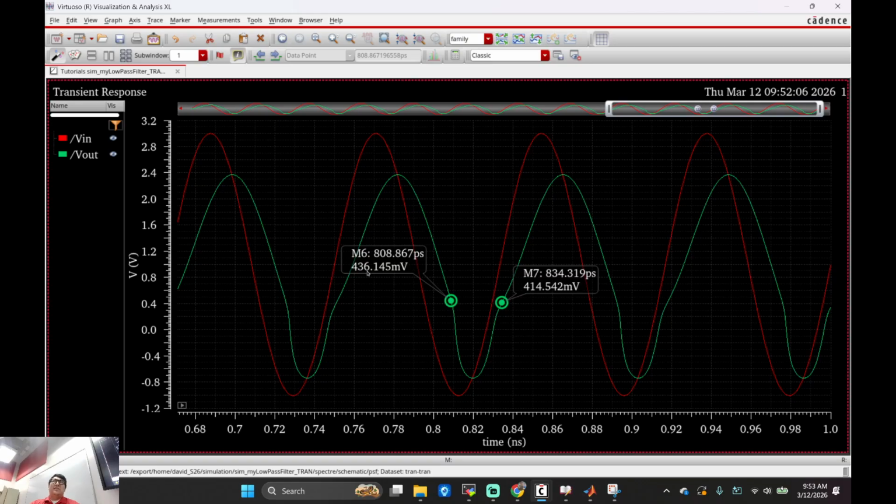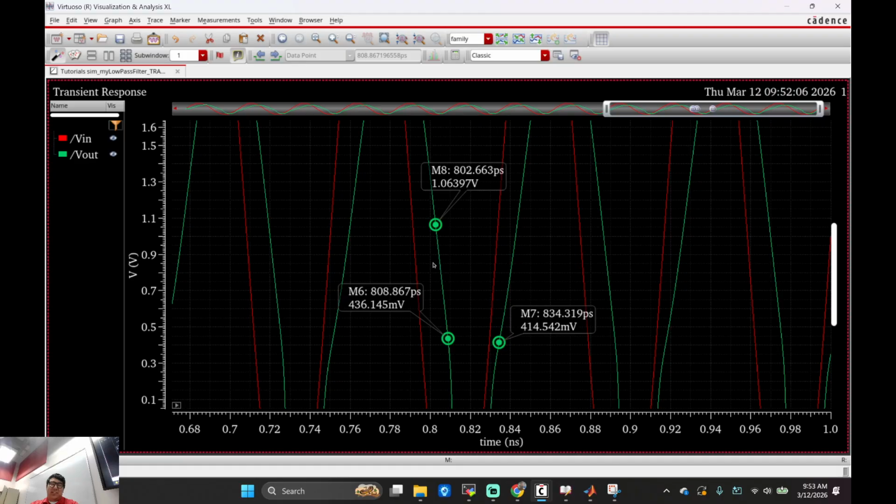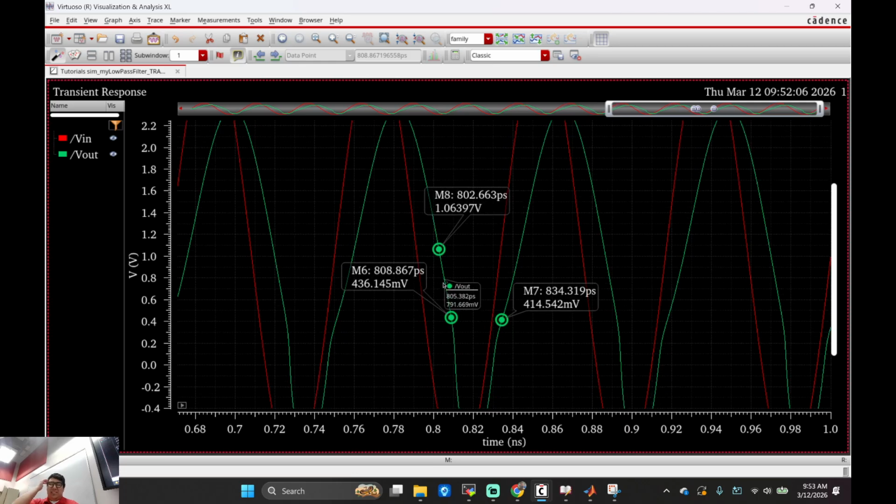So if you wanted to use the MOSCAP as a signal capacitor, you can. You just need to operate between, I'm going to throw out a ballpark number, 1 volt and 0.436, or 0.4. So yeah, you see this area right here? You can use it as a signal capacitor, okay? But then you're going to be playing with DC biasing, and it's going to be a hectic nightmare.